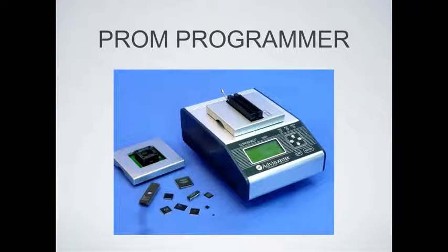So how do they program these devices? Well, here's a PROM programmer, but I could not find this programmer under that name. You do a Google search, and you say, I want a PROM programmer, you're not going to find one. It's going to come up with some odd results. But if you search for bipolar ROM programmer, then you're going to find this guy. It's the Advent Super Pro 6000.